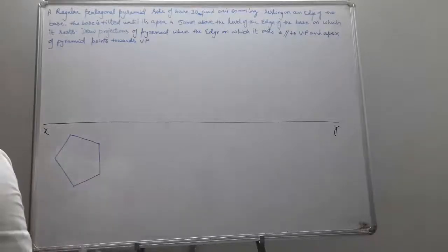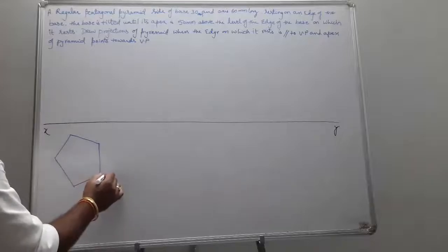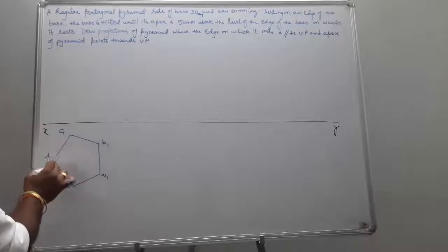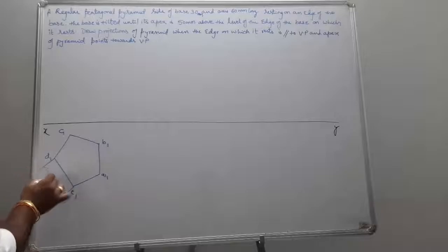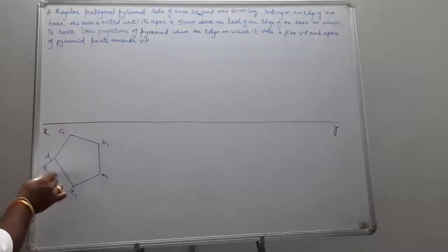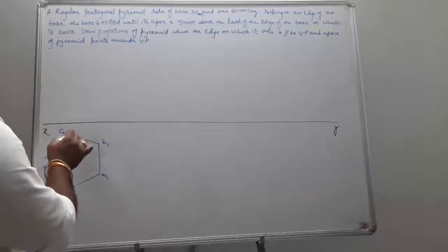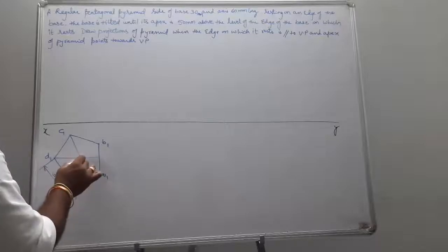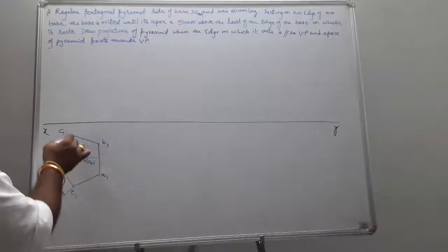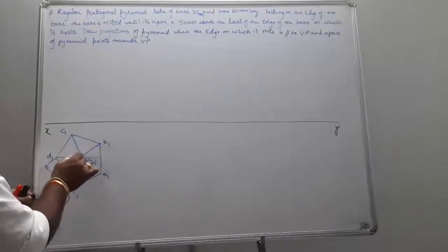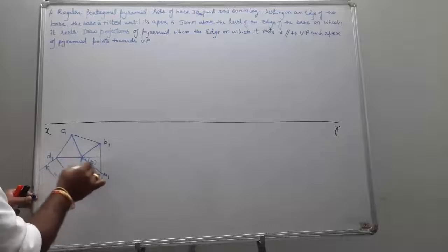Okay, so this becomes your A1, B1, C1, D1, E1. It gives the side of, what was the side? Given 30. It was a pyramid, so you are going to get only one set of points. Once we obtain your axis O1, that is the center O1 of O2, join all the corners to the apex. Why? Because it is a pyramid.